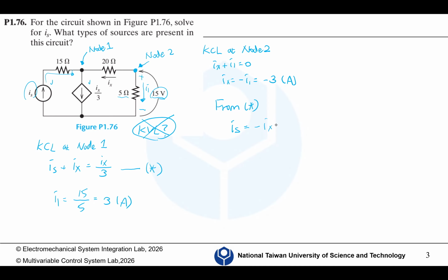Okay, so I2 is 2I1, then we can plug it into this equation. So, solve this equation, we have minus 20 plus 4I1 plus 6 times 2I1, oh, this should be 8, right? So we just combine them, we have 8 I1 minus 20 equals 0, then I1 equals